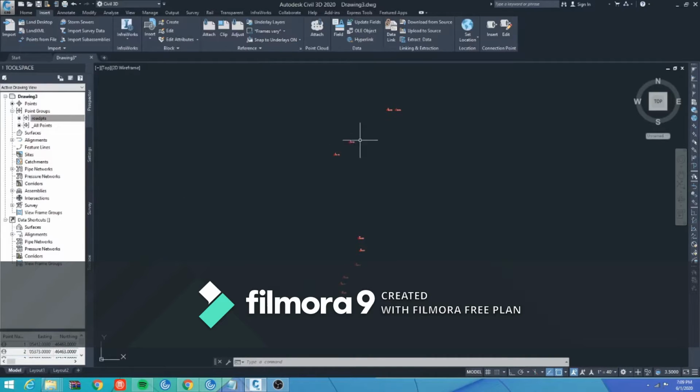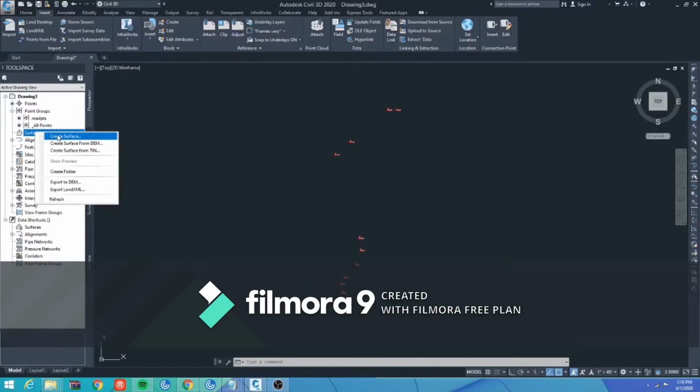Now with our point and point groups, we can create a surface based off of these points. A surface is a 3D representation of an area. Surfaces are made up of triangles and grids that are created from the points that we have just inserted into Civil 3D. To do this, we'll click on Surface, right click, Create Surface.